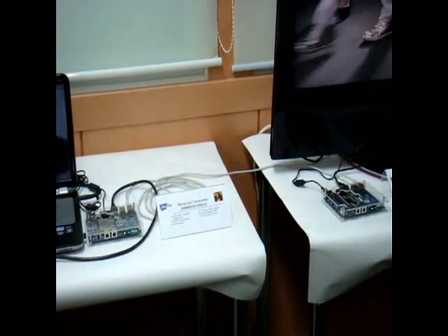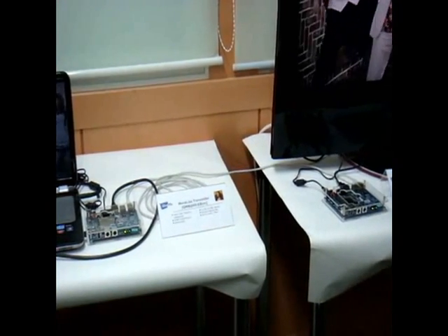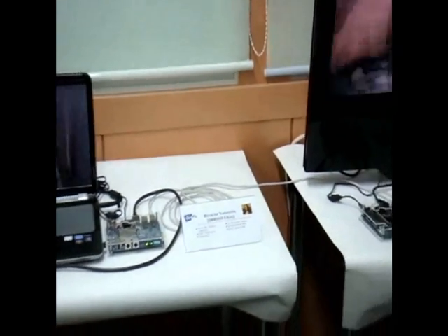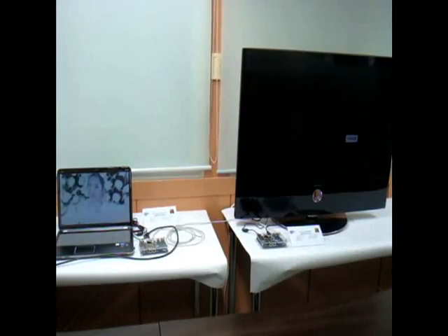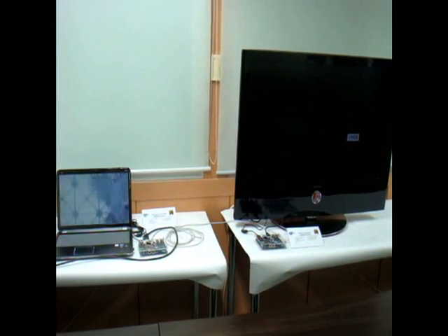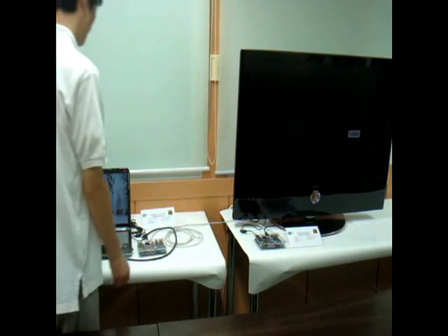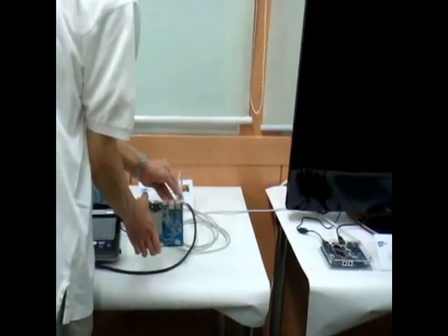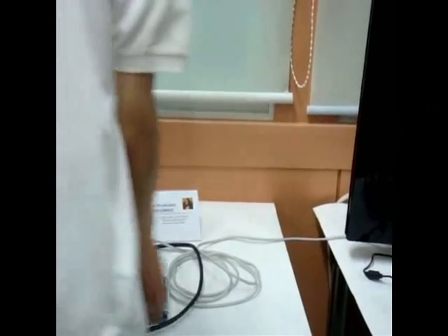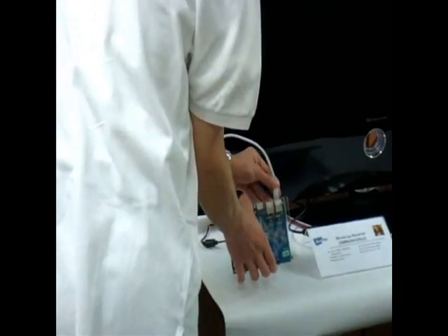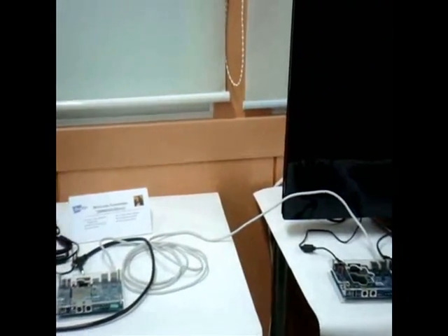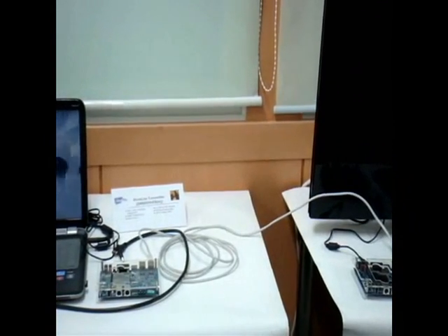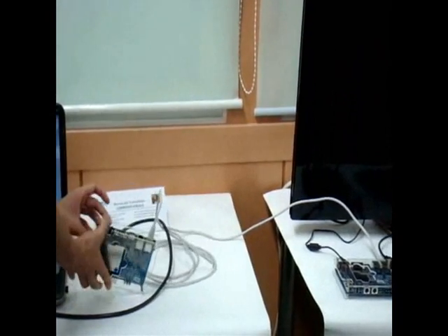For your better understanding, now I will show the whole connection demonstration with a notebook. You just gotta link the transmitter to the receiver with the Ethernet UTP cable. You gotta switch on the power after you check electricity is supplied to the transmitter and receiver boards.